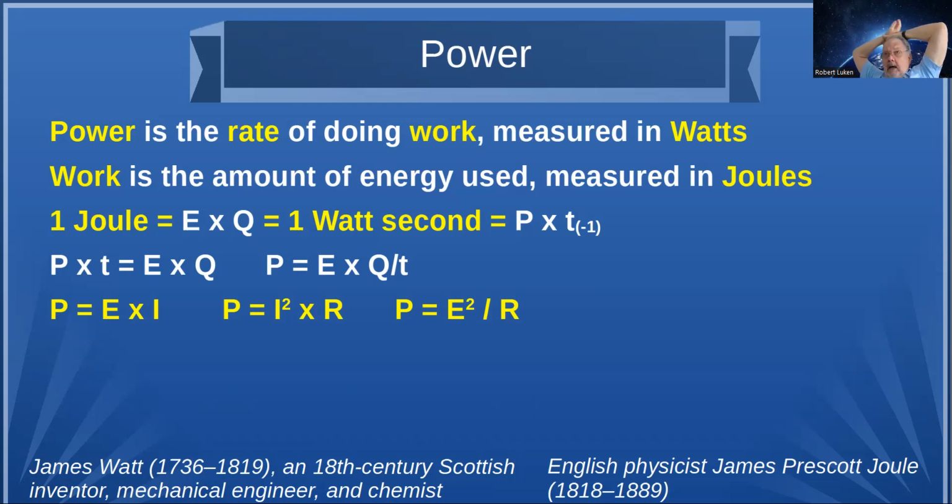And depending on how high that is above the ground, it's going to be in the 70, 75 ohm range. So when you hook a 50 ohm coax up to it, you're going to have an impedance mismatch and a standing wave ratio of about 1.5.